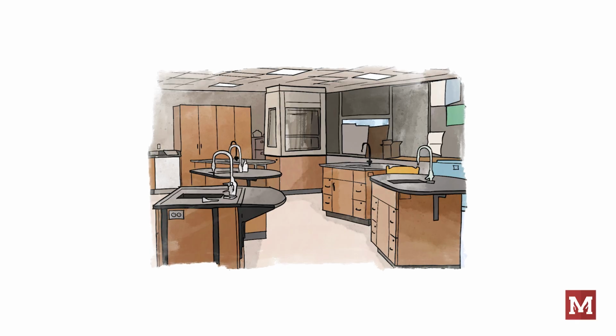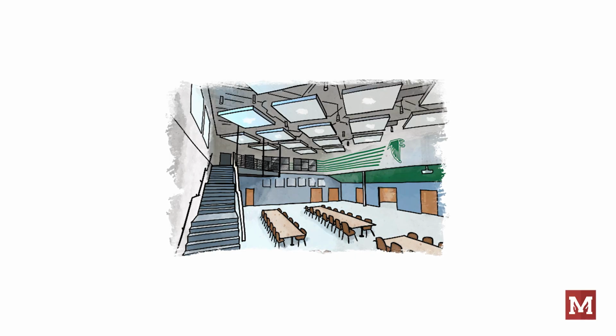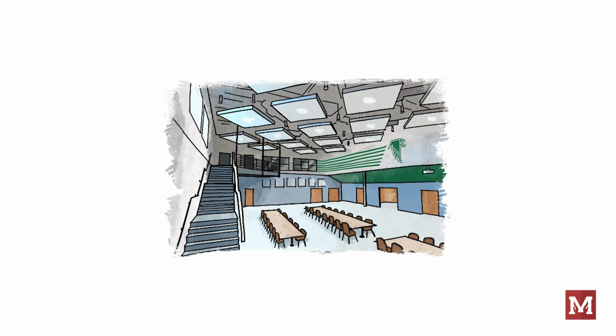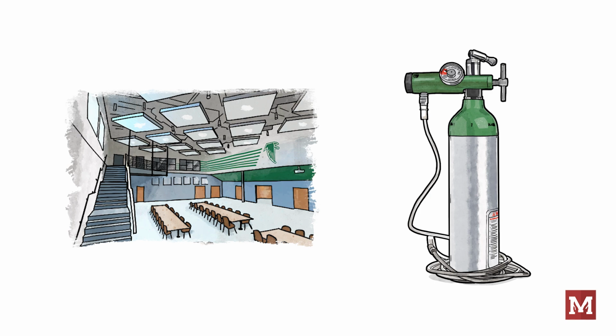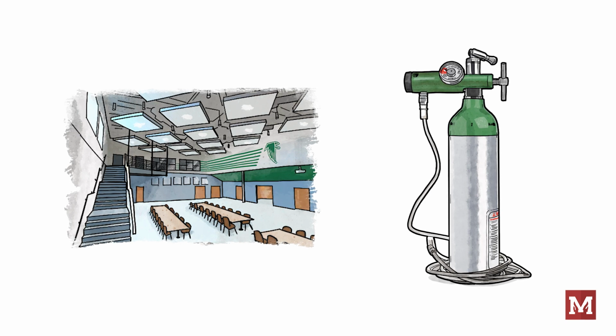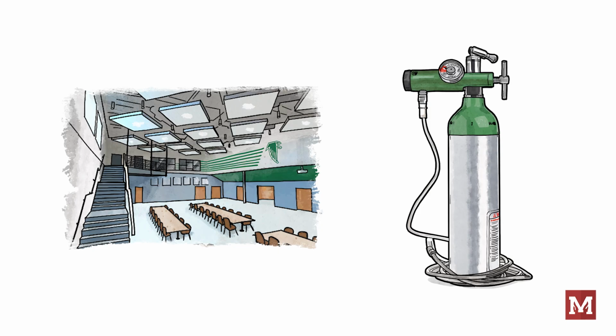Hazardous materials can be found in many occupancies. In large cafeterias, dining halls, restaurants, we find large quantities of cooking oils and other combustibles. They may also have some storage of cleaning supplies in larger quantities. A dentist office that uses nitrous oxide to help a patient's anxiety during cleanings or minor dental work needs to review the storage and use of this gas, as it's an oxidizer. It only takes 2 large cylinders of oxygen to trigger the fire code for a permit from the fire department.